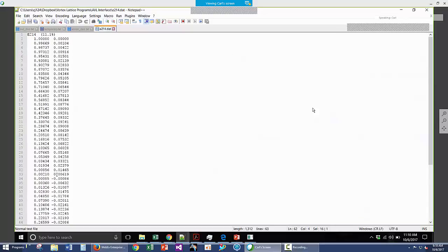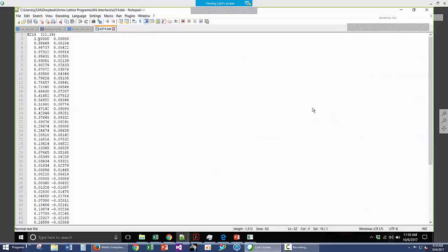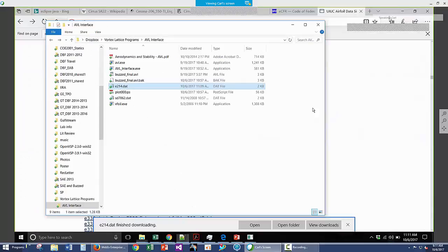That's the typical format. So occasionally you will find an airfoil that is not in this format. Sometimes they'll have the number of points in the second row and then it'll go maybe 1 to 0 and then 1 to 0 again, and you have to go through and reorder those. If you need help with that, I can help you doing that. It's not difficult. You can open things up in Excel, pull out the data that's in the wrong order, resort just a portion of it, and then save as a tab delimited text file, and it will still be readable with XFLR5 or XFoil or AVL that we're going to show. But that's the basic format that's being looked for.